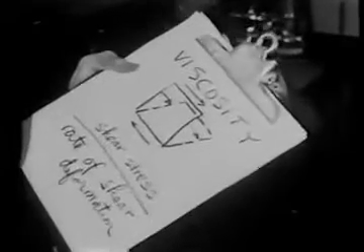There is one very important additional fact you need to know about viscosity, and that is that the fluid immediately adjacent to a solid surface cannot slip relative to the surface. What is more, the particular material of the surface, wood, metal, glass, plastic, cannot in any way alter the viscous behavior of the fluid.